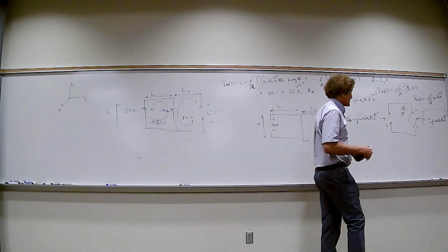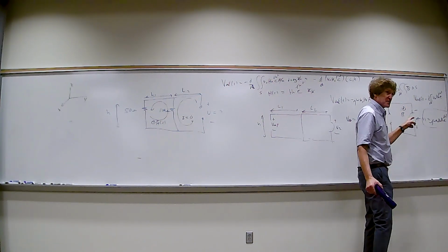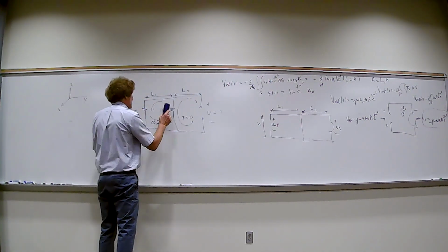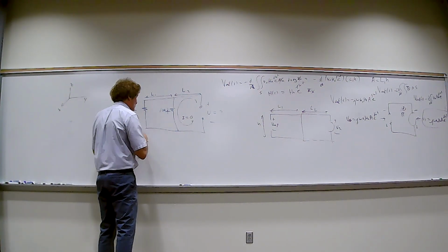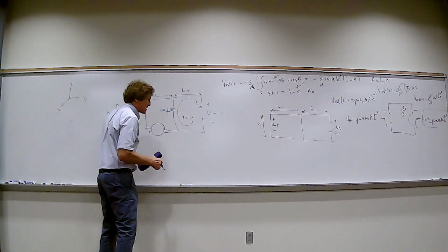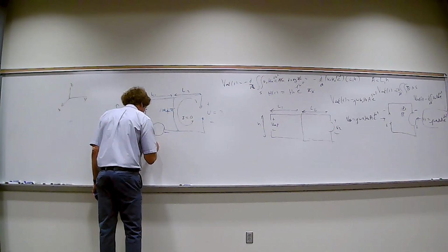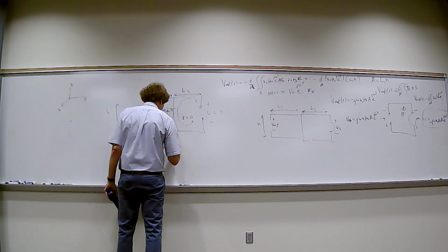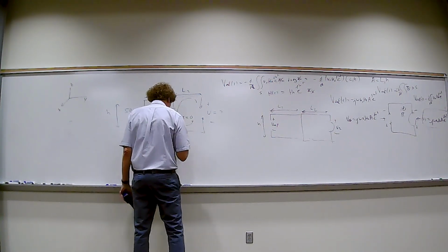All right, now getting back to this problem, here's what happens. Remember, the sense of that voltage is to cause current going counterclockwise. Y'all with, or clockwise, pardon, clockwise. You all see that? So what I can do is say over here, what I can really do, and I'm going to do it right here. This loop will have a voltage source. It'll be plus to minus, and the value of that source is going to be what I have there. Voltage here is j omega mu 0, and you might as well just put L1 times the height H. That's the voltage here, called V1,